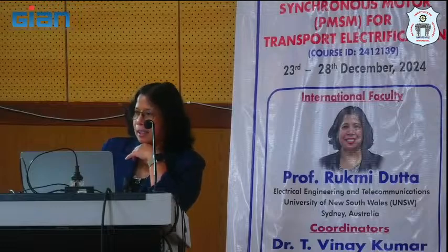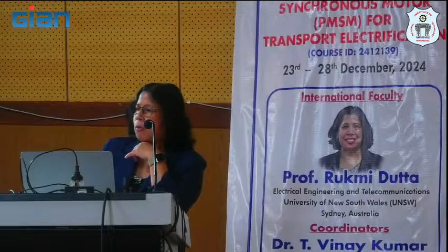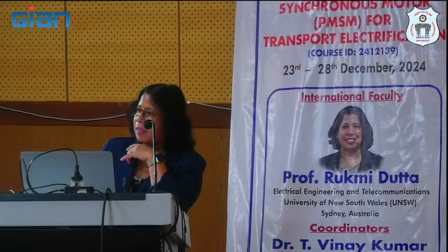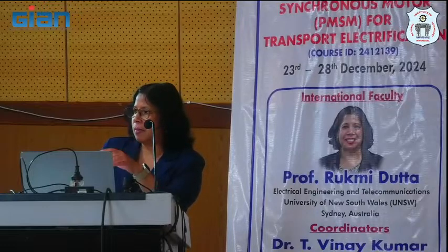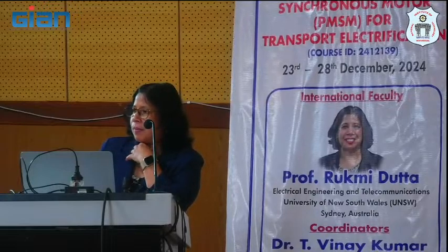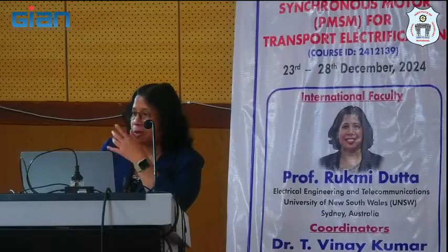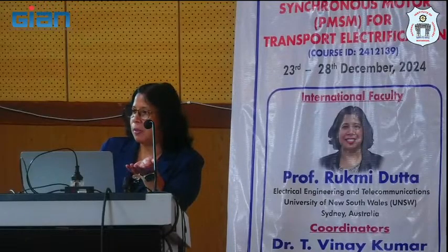Can we apply V/F control to a PMSM directly? You can, but it doesn't usually perform well. It's not an issue, it will start and it works, but the current will be very high and the position will not correctly match. The current will run behind. That's why the performance will not be good.